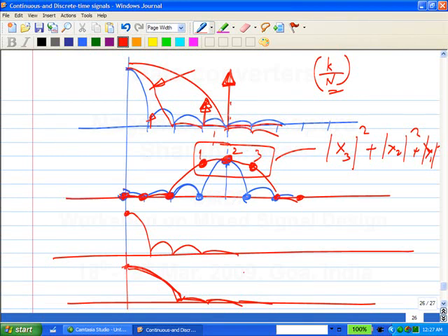For instance, let's say you are measuring an A to D converter. Okay. You will be taking some number of samples. Let's say 1024 samples out of your A to D. Okay. You can just take those 1024 samples and take the DFT as it is. That is one possibility. The second thing is you multiply it by this particular function with n set to 1024.